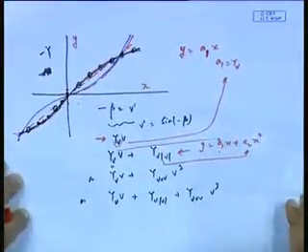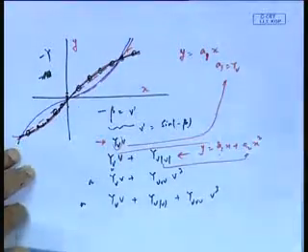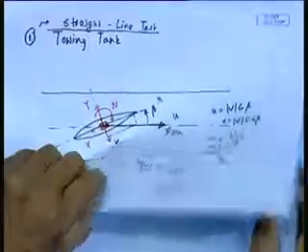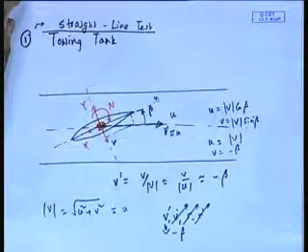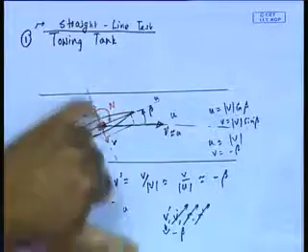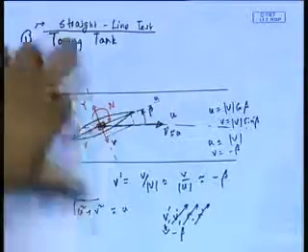Now, I just want to end this test at this point. If I do a straight line test, tell me what derivatives in this list I can find out. Where is that list? I bring that list and I try to tell you. The straight line test is very easily doable in a towing tank. I do not need a special facility for that, but I do need an instrument, a dynamometer that can measure Y and N. So, if I want to do it today in our towing tank, I may not be able to, because I do not have a dynamometer that measures Y and N.